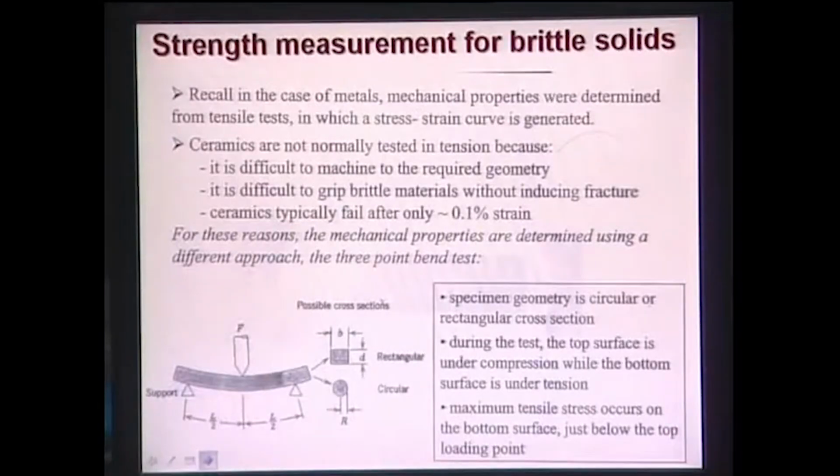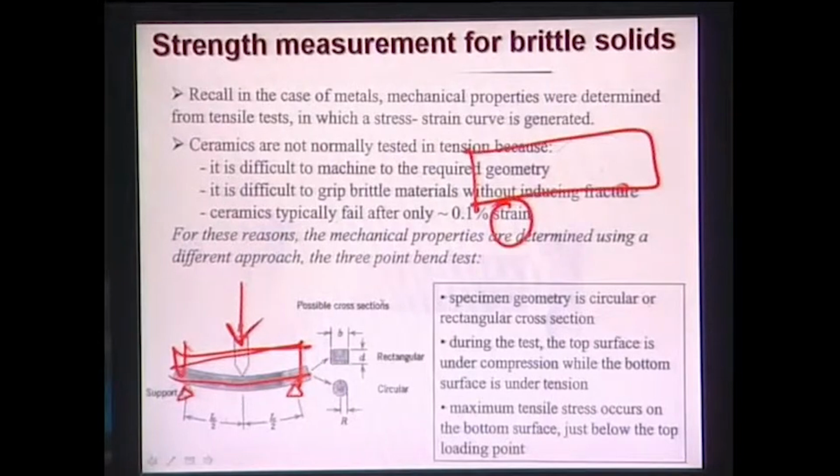Now, how can you measure the strength of ceramics? Traditionally, for metals you can measure strength by tensile force. But a tensile specimen for ceramics is very difficult to make. So what you do is make a flexure specimen and use two rolls. You place the sample on the two support rolls and break it by pushing from the top.